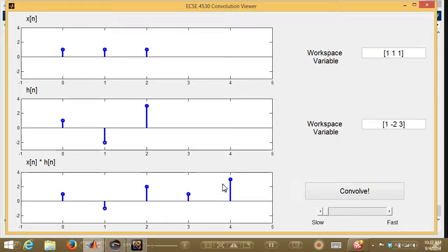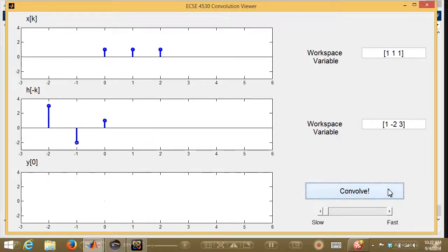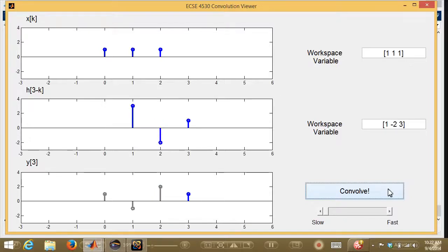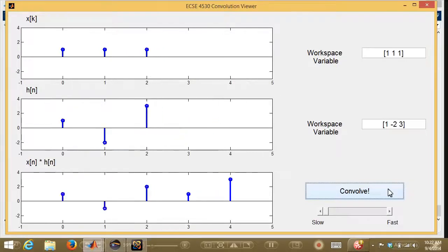So how does the convolution work? You're going to see that this h is going to flip around, and then I'm going to start to click it across the x, and at each point I sum up the corresponding entries. So let's watch that work. Here's the flipped version. Then I get one entry here, I click the signal over by 1, I add the corresponding entries up, I click it over by 2, by 3, by 4, and by the time I click it over by 5, the signal has already left any overlap with x. So let's watch that again.